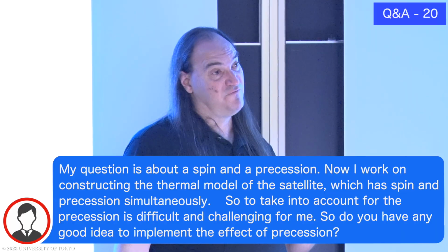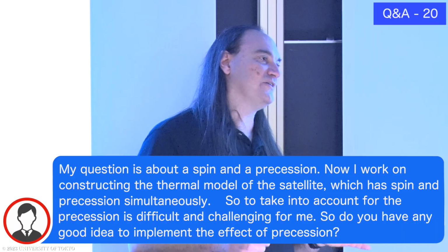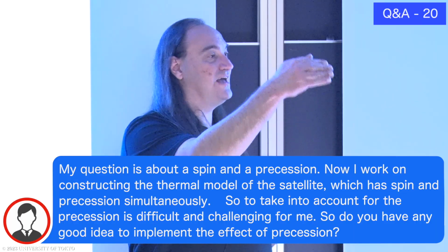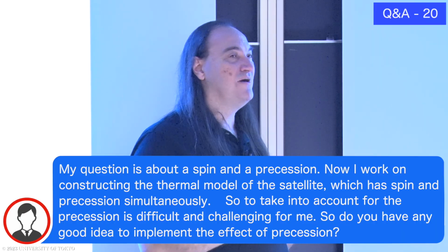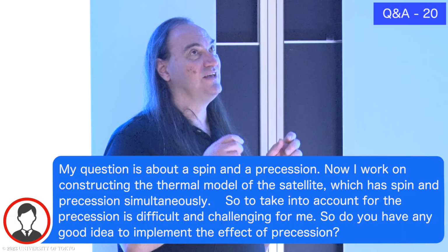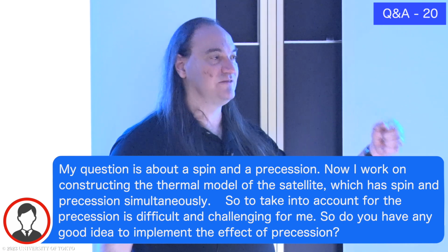And thermally, when you're solving, also do that, because you don't want to solve your calculation points at an integer multiple of it, or you're going to always get the same loading on the same sides and not get the behavior. So think about that when you have something that's rotating, to introduce some quasi-randomness so that you're not always solving at the same point.